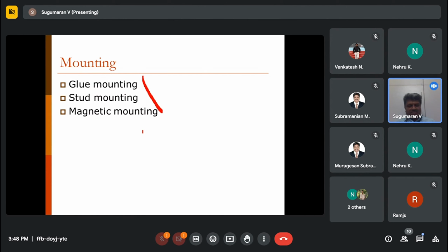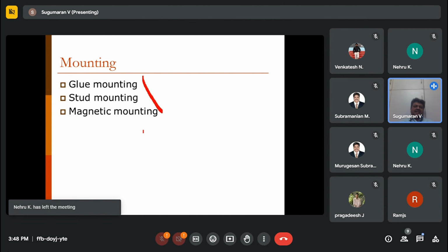The question is simple. For that you should look at the price and what is the range of frequency the mechanical system will give. The biggest challenge in vibration measurement is that before even measuring once, we may not know what range of frequency a machine will give.